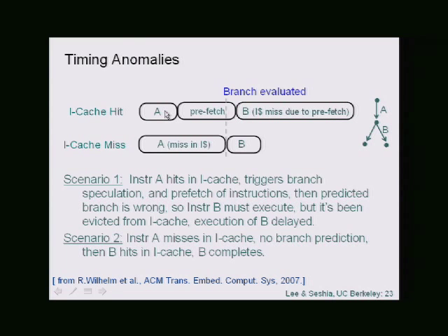Doesn't that seem like the prefetch stage was the problem? Exactly. Yeah, that's the point. The prefetch stage did not happen here, and it happened here. But I think the issue that is being brought out here is that if you just focus on one part of the processor, and you say an instruction cache miss is always the worst case, right? Let me just do this part analysis based on the instruction cache miss state at this point, and optimistically assume that this will never lead to a worst case situation, then you would not find the worst case execution time.